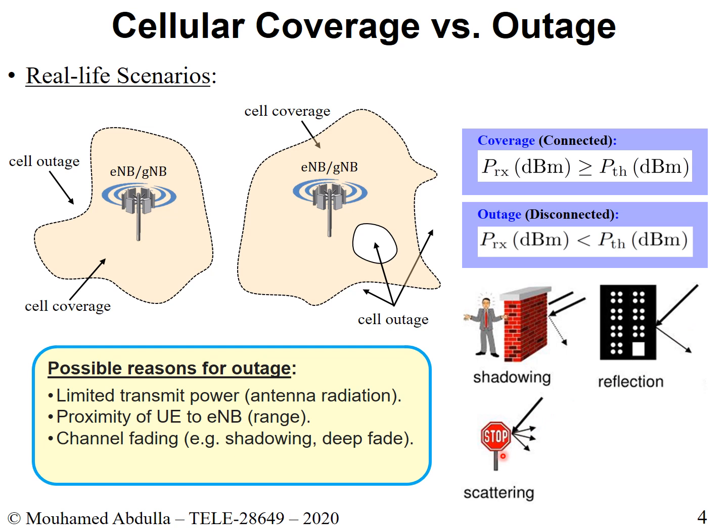Scattering generally happens when your signal hits small objects, for instance bushes, small trees, or infrastructure on the streets, like a traffic sign, like this one here. The signal touches it, it's a small object, and suddenly the signal travels in completely different directions. These are all different ways that could vary the type of coverage that you have, and to the extent that it could also bring you into outage.